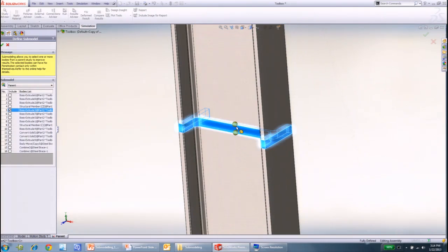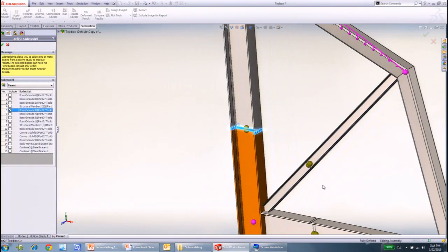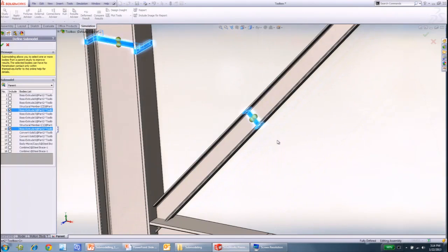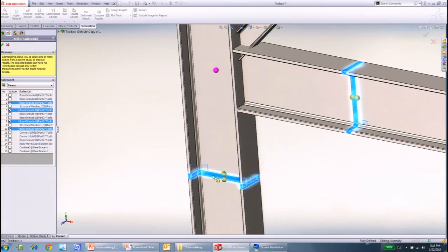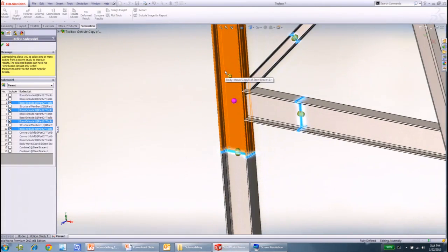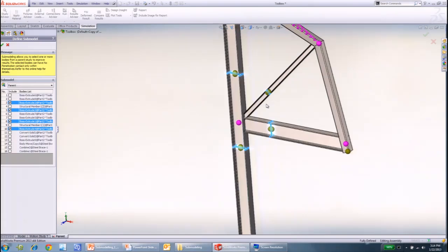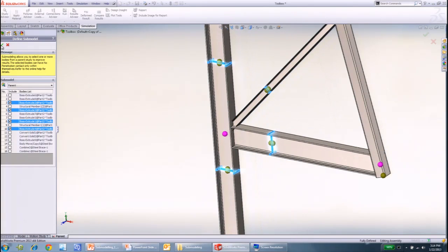So I don't need the internal geometry because I'm just going to replace it with more details. You can use the existing geometry and just make hole cutouts or add more details, or you can just replace it with new geometry inside without changing the physics. I'm just transferring the displacement fields here.